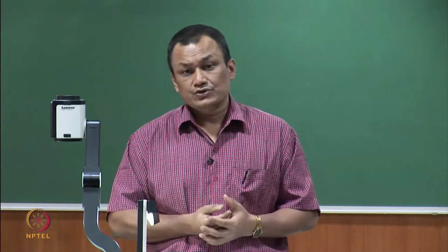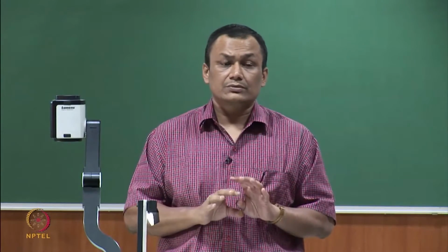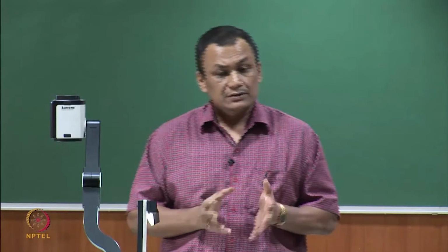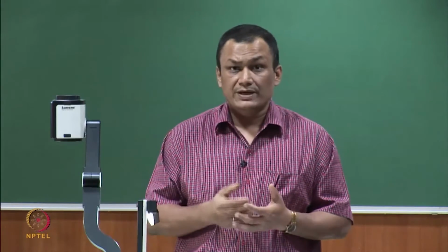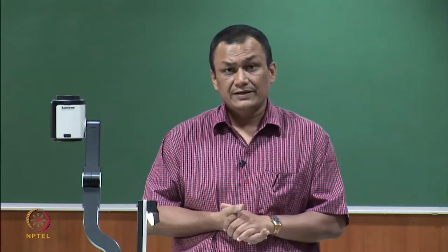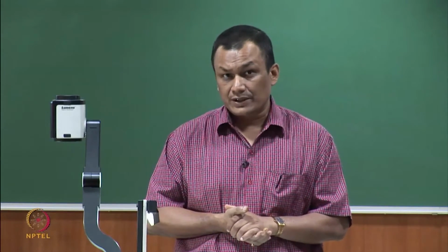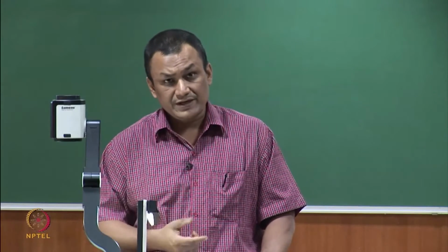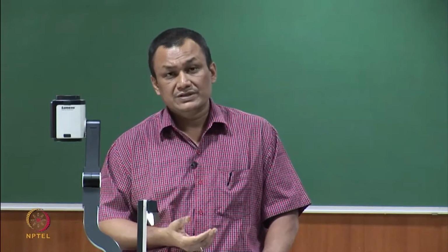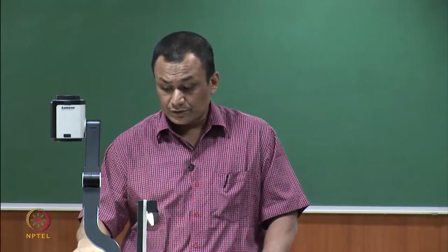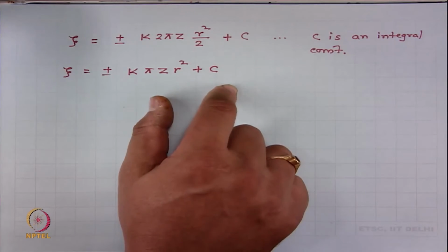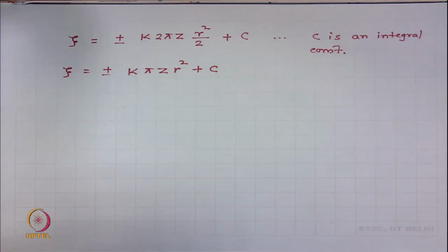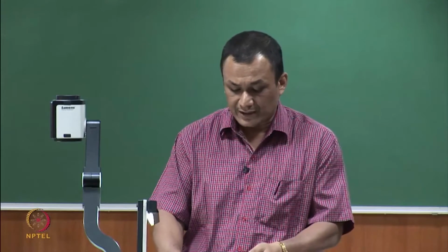In order to avoid those two problems, we considered two approximations. One is k value is very high, slow migration, period of migration is very high. Second, tan square beta much less than 1. Based on these two, we found that the approximated equation was defined for small radius, and also the analytical solution is possible. In this way, by introducing two approximations, we could solve the problem associated with the radial migration of fibers.